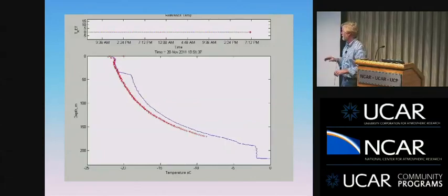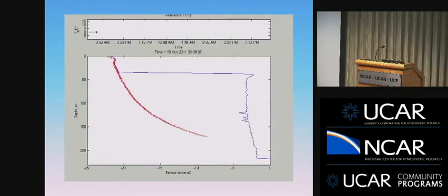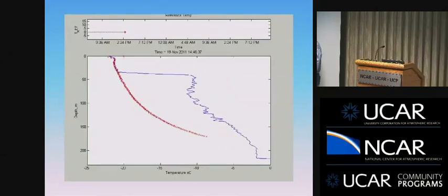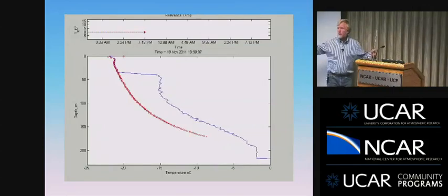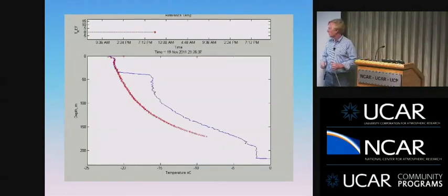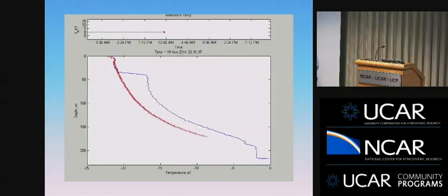Stop. And we lowered an optical fiber down into this open borehole, no water in it. We lowered it down, and this is the temperature profile we got after about 2 or 3 hours, just letting it equilibrate. Okay? So each one of these crosses represents a temperature measurement integrated over a meter of the optical fiber. So a couple of important things on the red line. Let's not look at the blue line yet. First off, the temperature profile is curved down to the ocean. The ocean's going to be right about there. Okay, why is the temperature profile curved?